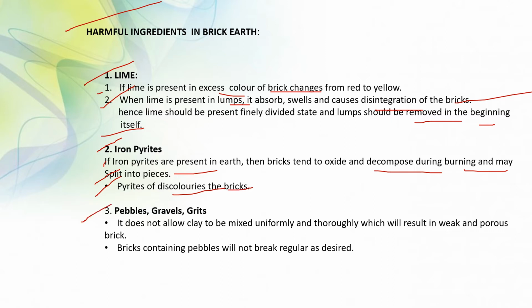Next, pebbles, gravels, grits. It does not allow clay to be mixed uniformly and thoroughly, which will result in weak and porous brick. Next, brick containing pebbles will not break regularly as desired. I hope everyone understood.